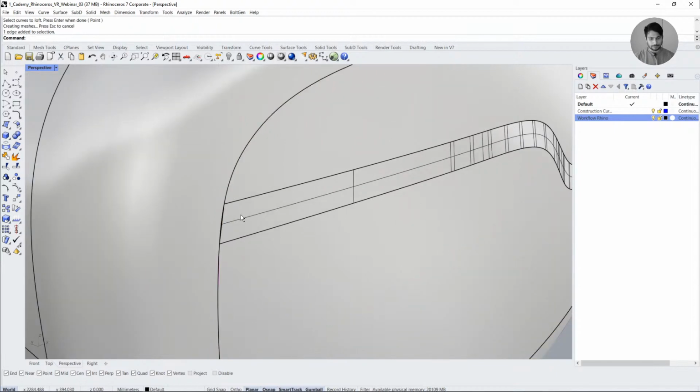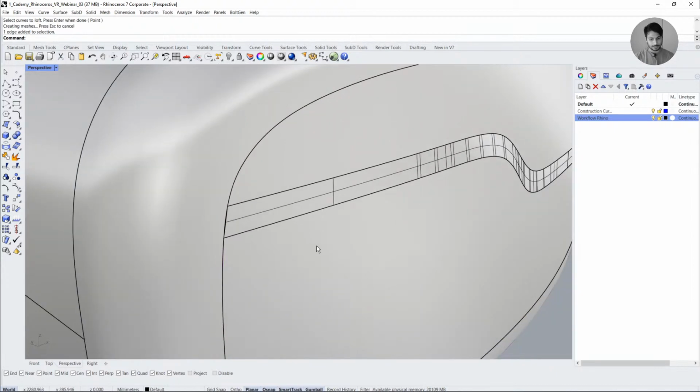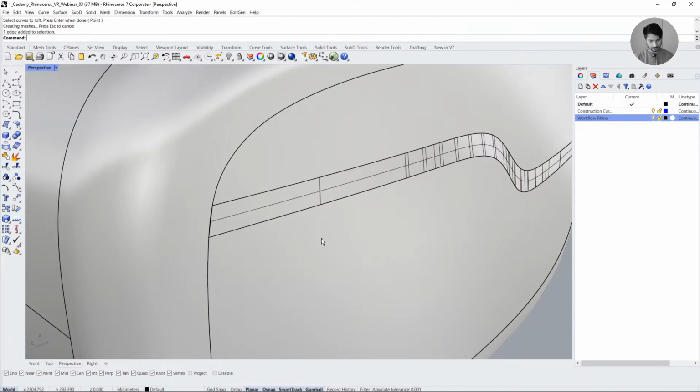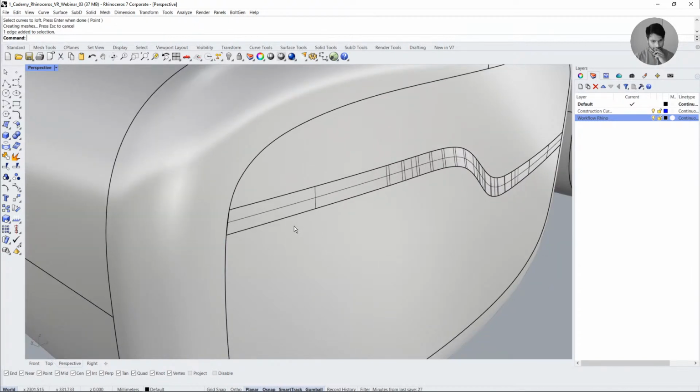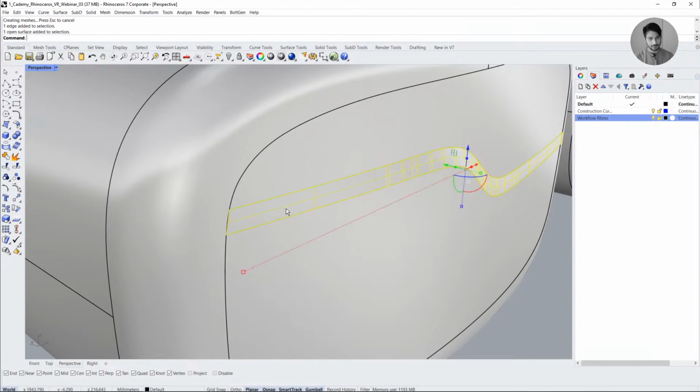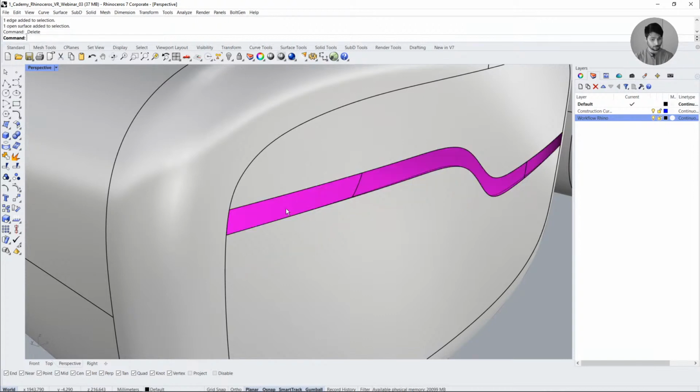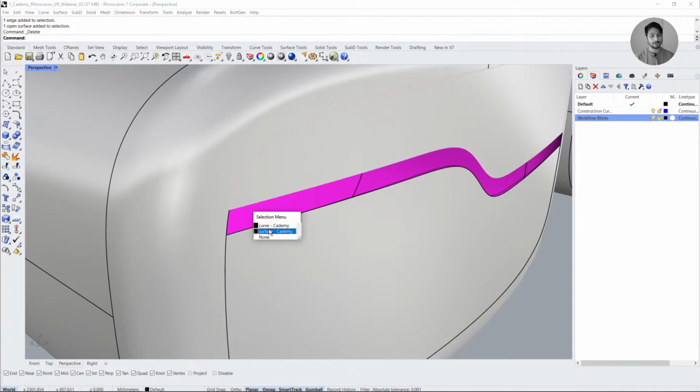So what can we do? A lot of you are saying bridge. Bridge is probably in SubD, not in NURBS surface networks. BDE concept, you have the right answer. It's Sweep 2. Rishikesh, you as well. Faisal, you as well, thanks. So we are going to do Sweep 2.